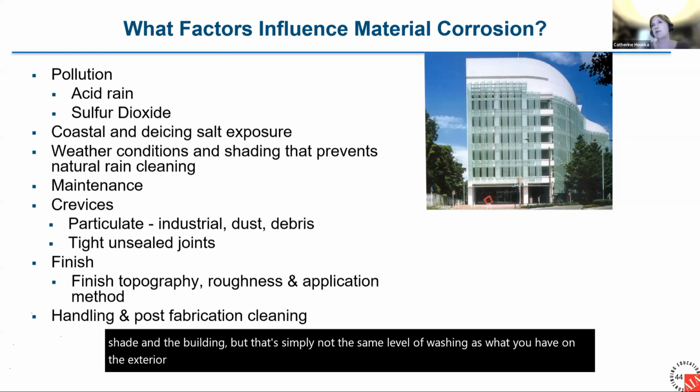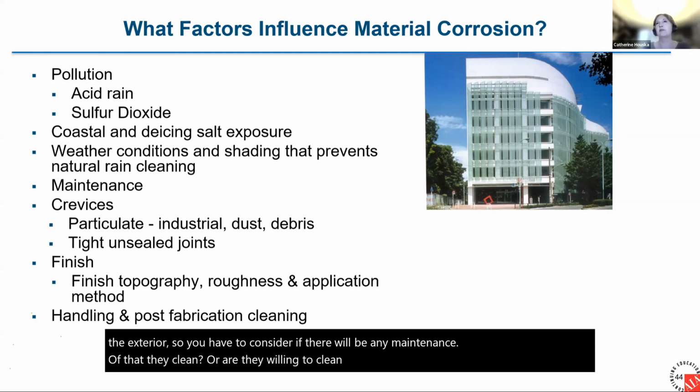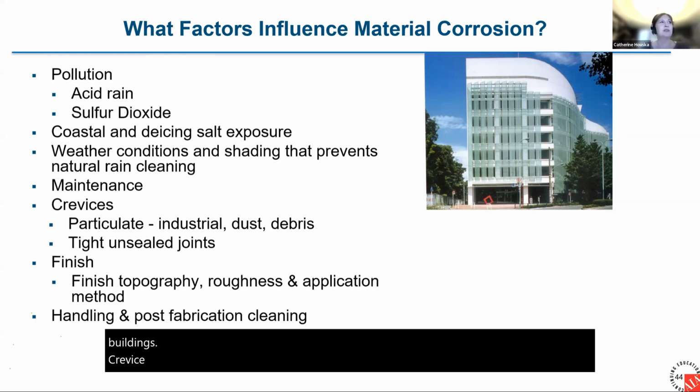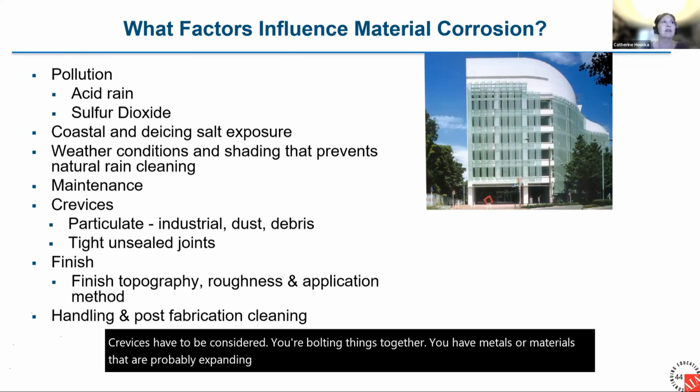So you have to consider if there will be any maintenance of that. Are they willing to clean the back of the panel and the structural sections as they clean windows? I've never seen it happen, but perhaps it would on some buildings. Crevices have to be considered. You're bolting things together. You have metals or materials that are probably expanding and contracting. So if you have tight unsealed joints, it is possible you could have crevice corrosion there.